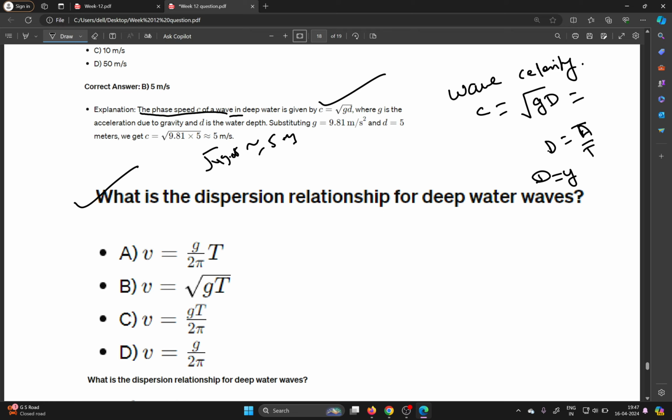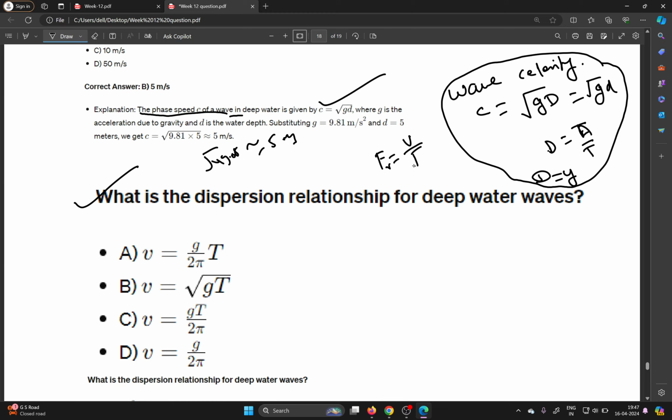Due to this criterion, you can correlate from your open channel flow expression. Here we are talking about the wave celerity in terms of c, for a very wide channel. Also you know the Froude number, that is V by root of gD. Nothing but your Fr is the average velocity, always remember, divided by your wave celerity, you can say also.